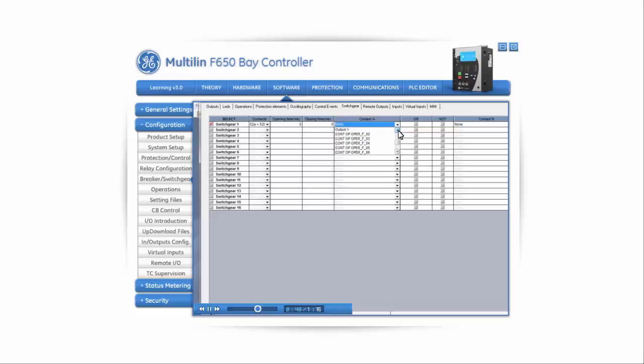For this example, we shall choose two different contact inputs for Contact A and Contact B. We will use the contact inputs 1 and 2 of board F, respectively. You can also associate an open text, closed text, and error texts for 00 and 11 errors. These error texts appear whenever the status of the 52A and 52B are the same, either 00 or 11.